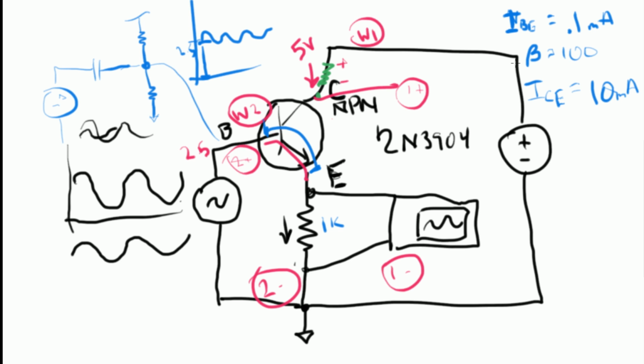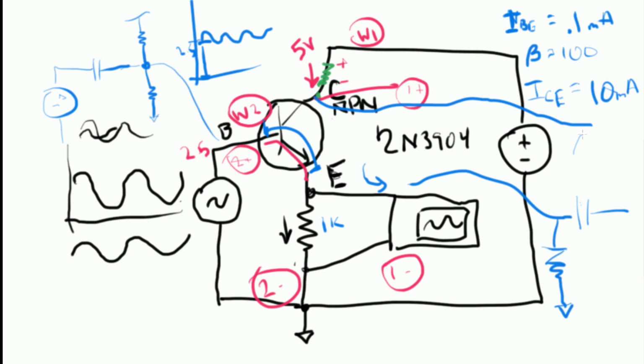And then the idea being that we use that current gain to amplify, well, a couple things, right? If we're doing an emitter follower, we might use this current going not to the scope but out to another circuit out here. You might use it to drive some additional stage over here. You might have a load resistor here. There could be a bunch of options there. If we're doing not an emitter follower but a common emitter, that's when you pull the voltage off of here, and that's what we're kind of looking at here. You have a larger signal gain based on this resistor up here.